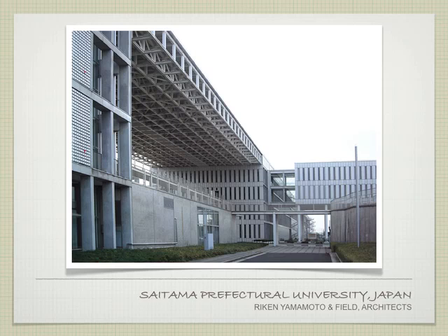So basically what they did is they took the building and they added cast in place. Right, this is where I'm getting to your question, right? They said, here's our precast building. It's not particularly stable, so what do we do about it? And so they took the front of the building and the back of the building in this tower, right, and they said, we're going to pour site cast tubes, right, on the back half of the building, 2 tubes, and on the front half of the building, 2 tubes, right? And those 2 tubes in the front and the back are providing our primary structural lateral loading strength, right?